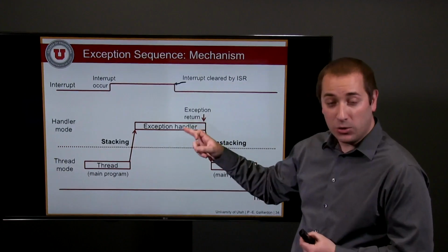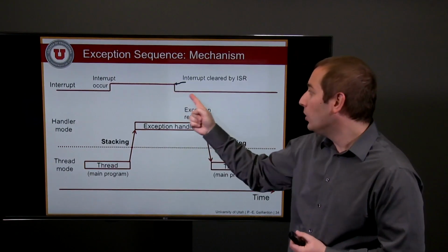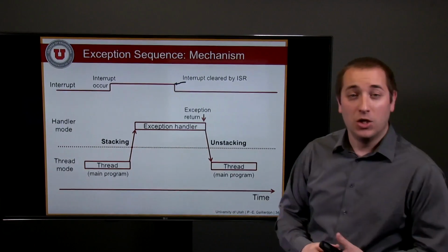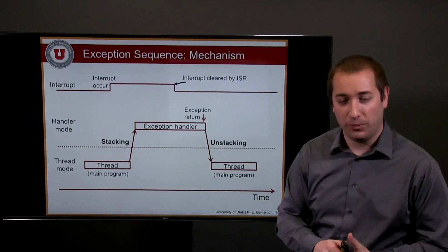Once you're done with that, or as part of the exception handler, should I say, you also do have to clear the interrupt flag to tell your system that you actually properly processed this interrupt.